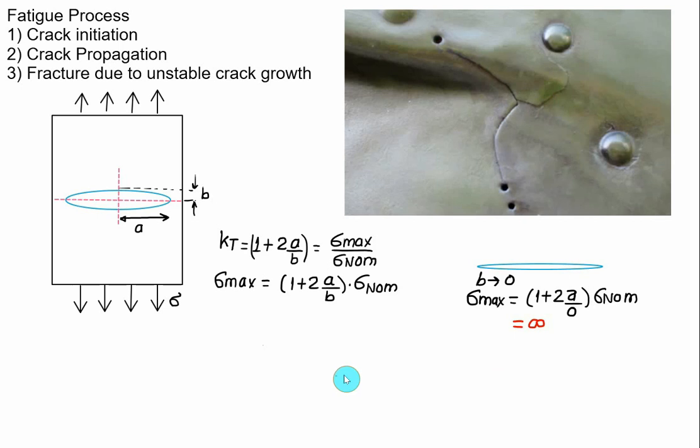As far as brittle material is considered, as compared to ductile material, brittle materials are the materials that can fracture without yielding, but the brittle fracture is not instantaneous. Crack propagation needs time. For that we require energy to feed the crack, and only then will the crack propagate.